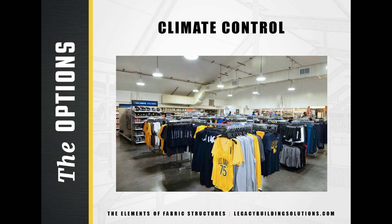Metal buildings are constantly contending with air leakage through screw holes and seams, which is another avenue of heat loss within a building. An independent study of an insulated fabric structure found it to be 157% more airtight than a conventional insulated metal building. Flexible fabric also allows for reduced air leakage through the wall assembly as well as fenestrations.